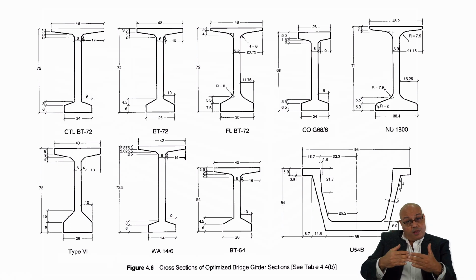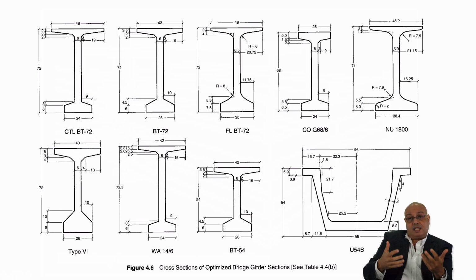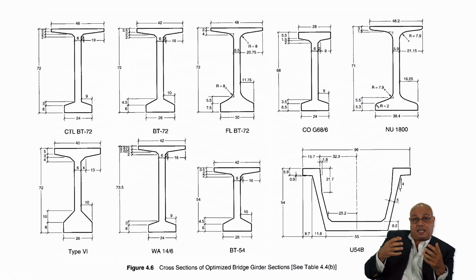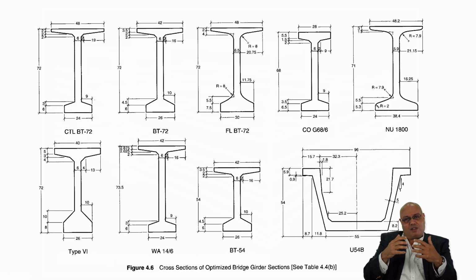Then move to another level and put steel reinforcement at the tension side, which will increase the moment capacity. So you're going to have a nominal and ultimate moment capacity that is way bigger than what you had for plain concrete, for a reason. Because the concrete, as we know, is strong in carrying compression, which is at the top of the beam. But when it comes to tension, it is not behaving very well.